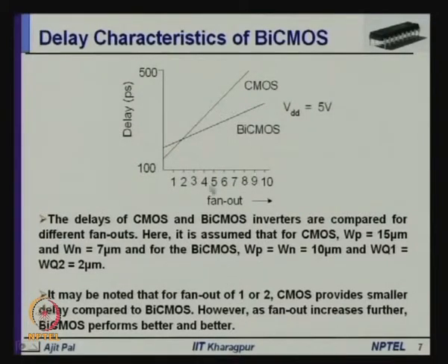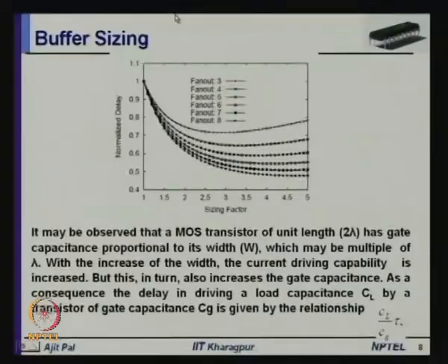So, we have studied the delay characteristics of a BiMOS inverter compared to standard CMOS. Okay, now let us switch gear and come to the last topic, that is your buffer sizing. You can see here an experiment has been carried out to see the normalized delay for different fan out and different sizing factor.